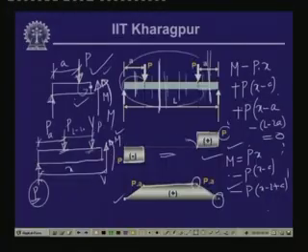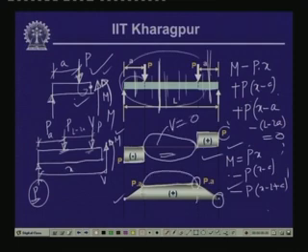So, if shear force V is equal to 0, then the moment at that particular portion of the beam is expected to be constant, and that is what is reflected over here. Now, in this particular zone, as we can see, the value of the shear force is equal to 0, and hence the value of the bending moment in this zone is constant, and here it is linearly varying from 0 to Pa and from Pa to 0.